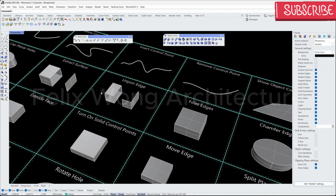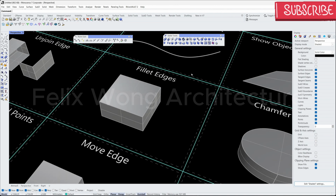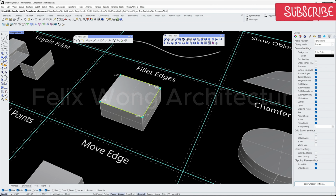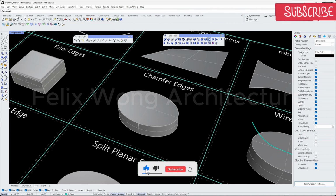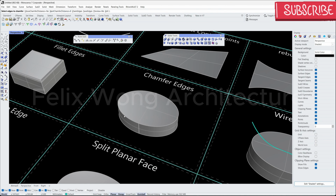Use the Fillet Edges command to fillet an edge in a shape, set the radius in the command bar. Select the edges and press Enter. To chamfer an edge, choose the Chamfer Edges command, specify the distance in the command bar, select the edges and press Enter.